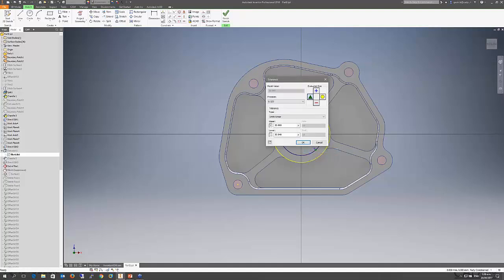By clicking on that tolerance box there, it brings up a little tolerance window. This allows me to set limits or fits. If I pick fits, then I can choose from the common fit codes from that table in the book that I mentioned before. But in this case, I've just got limits stacked. I've just got a simple tolerance here, which is 30.06, 30.04.